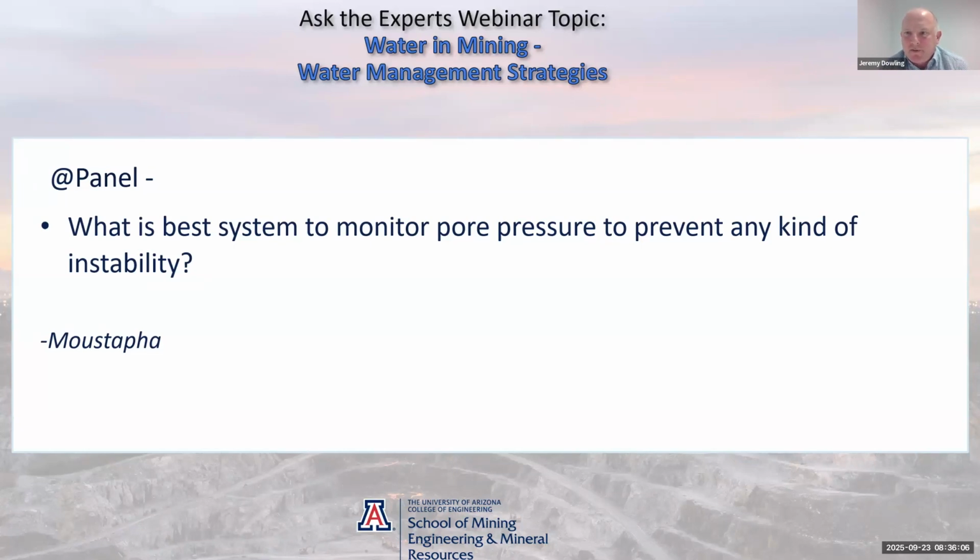So, for example, if there's risk of shallow structural instabilities high in the slope that may have pore pressure as part of the mechanism, then try and gear the monitoring system design and layout towards measuring pore pressures in those shallow structures, and making sure that the sensors are actually placed on some of those structures that may be the potential failure mechanism.